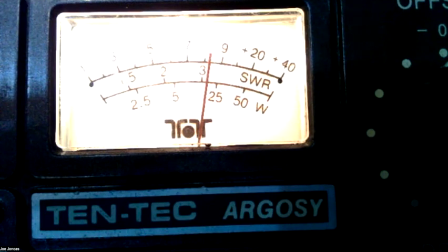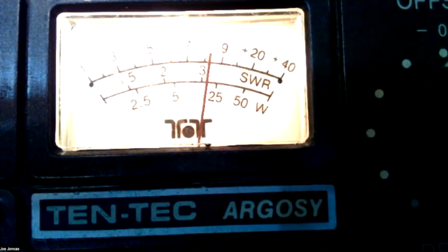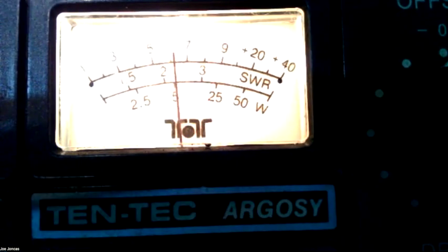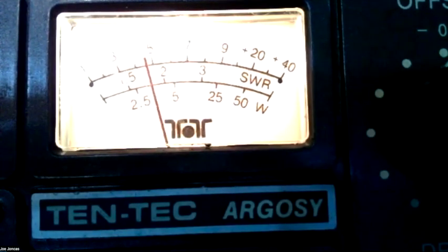Now, 6 dB in voltage is the same as 3 dB in power. So if you cut your signal from 100 watts down to 50 watts, you lose 1 S unit. So why are we using, oh, this is where we just had the convention, right? This S unit. I mean, why don't we just stay with dBs?